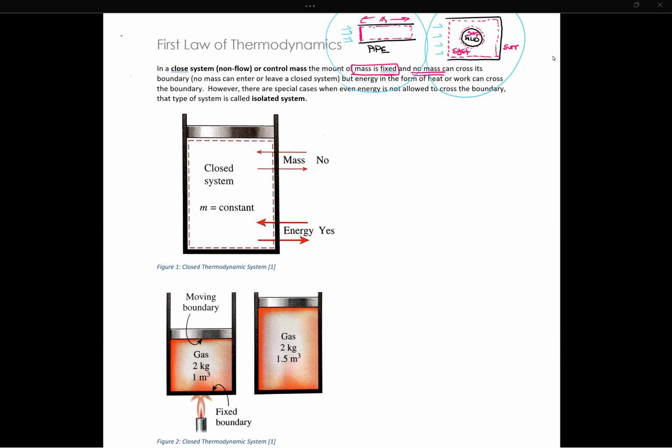We're going to review what a closed system is in thermodynamics. In the first law of thermodynamics, energy problems, the simplest type of problem is a closed system or a no-flow system. Some people call that a control mass system. I don't, but I call it a closed system or no flow. So basically, m dot equals 0 is what I would write at the top of my paper if I were to get a closed thermodynamic system.